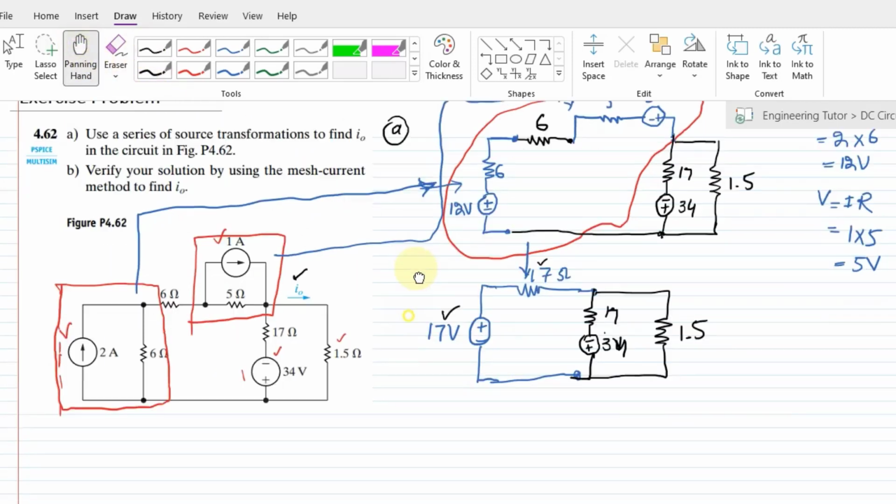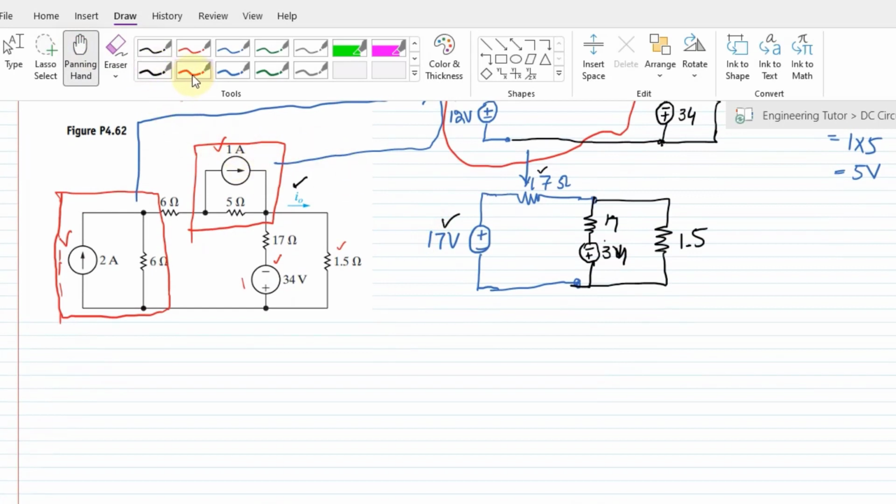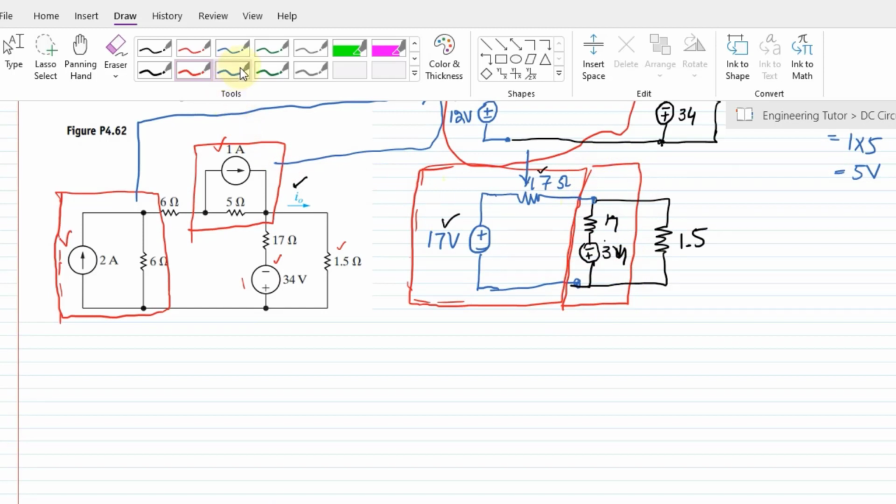So now, in order to transform them again, I will see here that this circuit, because both are in series. Similarly, this one, these 2 can be transformed here now, and by transforming them, I will get a current source here and the same resistor, which will be of 17 ohm, and the value of this current source has to be found out.